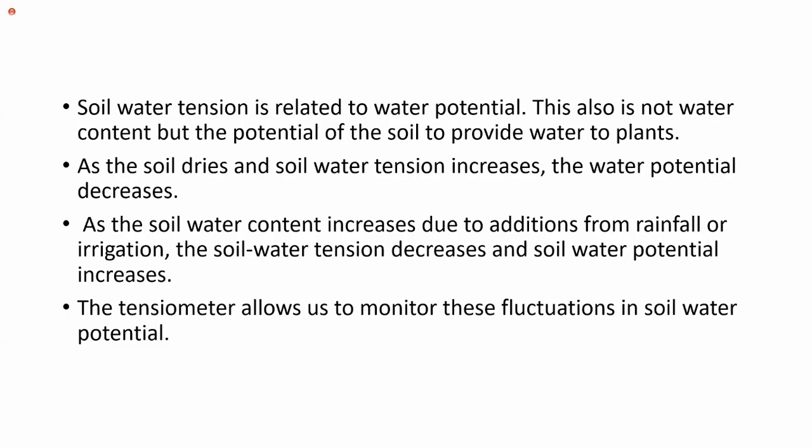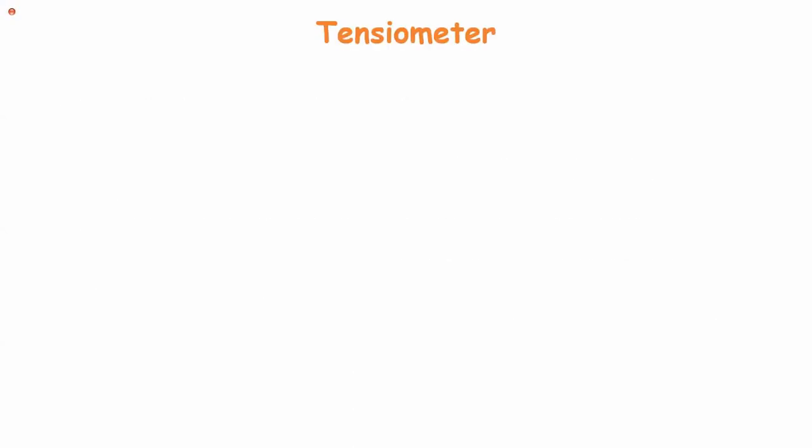This tensiometer measures the soil water potential, and we calibrate what the moisture content is for different water potentials. Then after we get a graph, at any time, if we measure the tension or water potential, we can get the moisture content.